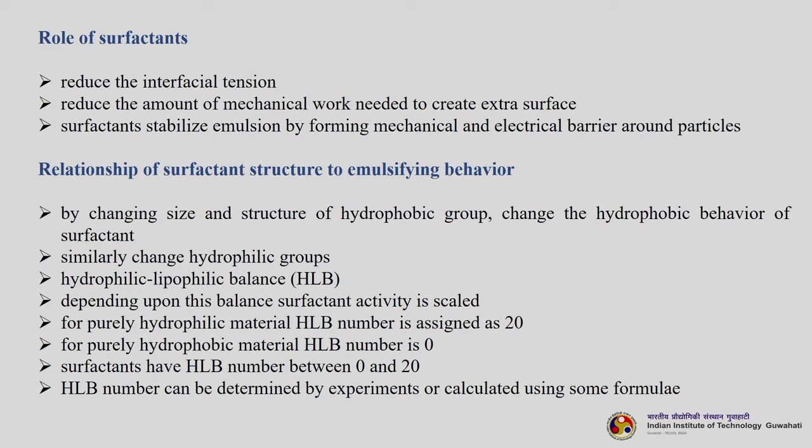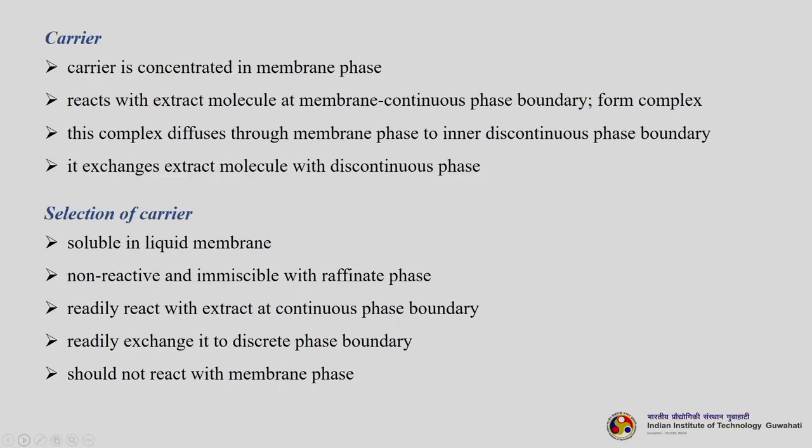For purely hydrophilic material, HLB number is assigned as 20. For purely hydrophobic material, HLB is 0. Surfactants have HLB number anything between 0 and 20, and HLB number can be determined by experiments or calculated using some formula. Now carrier. Now carrier is concentrated in the membrane phase, it should be dissolved in the membrane phase,